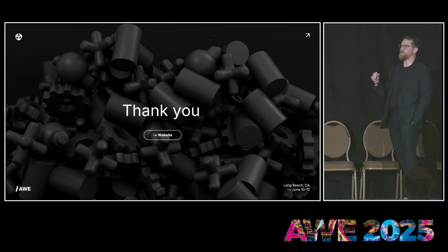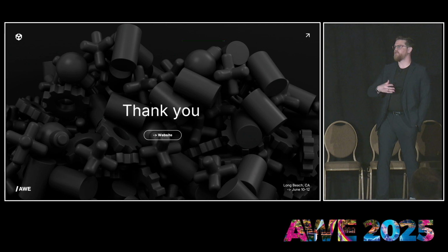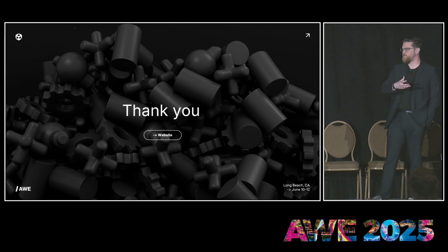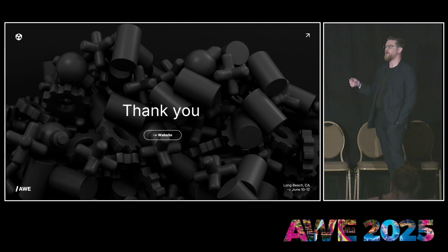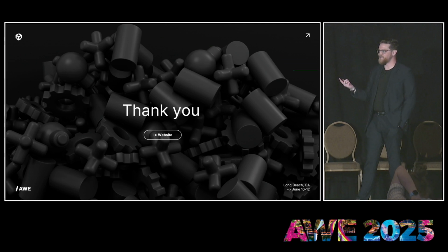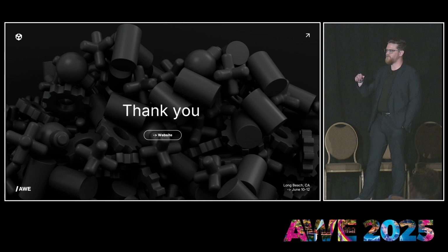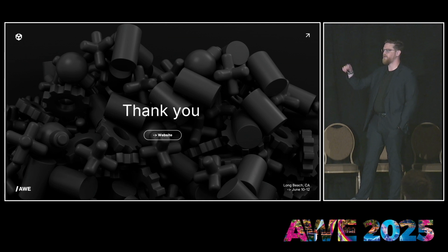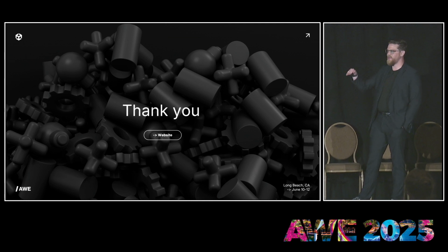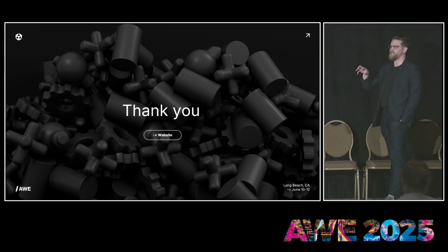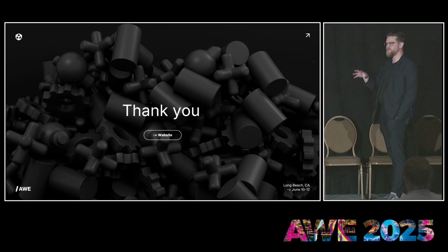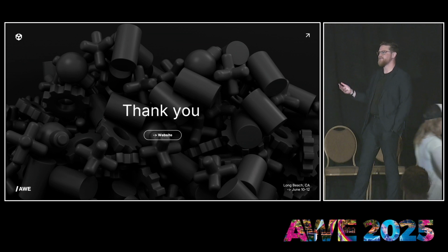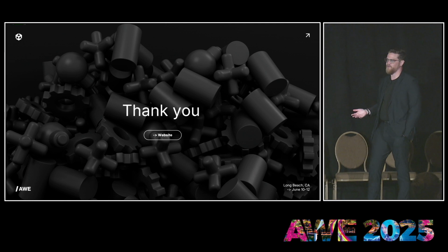I would expect that if I have, let's say, a factory floor that is a Navisworks file versus a small engine that is an assembly file, what I would likely want to do is leverage that automation system and create nodes that effectively say, hey, if you're bigger than this scale, cull that out entirely or decimate at this level. If you're meeting these metadata requirements, I want to preserve this piece of that. You'd probably find that you would modify it and have a different process for each type of file, but not necessarily that there would be any difference in the expected quality output.